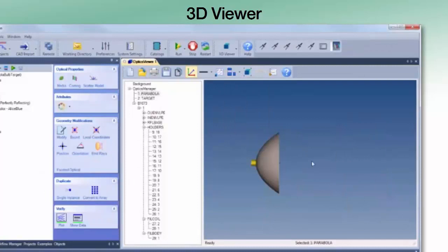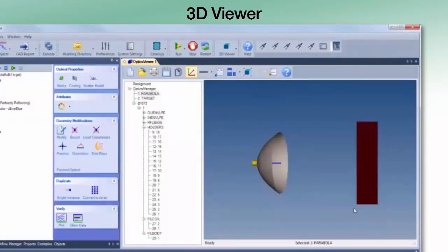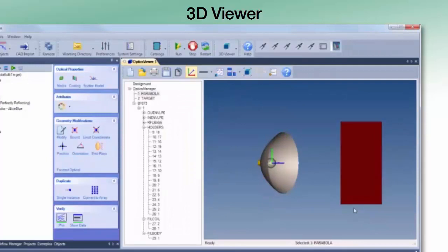So if you happen to be on a system that doesn't have a center mouse button, if I use the actual arrow keys on the keyboard, the left arrow key will rotate by 15 degrees about the vertical axis. So that's a 15-degree rotation. Let me rotate 3 increments, and so I have now rotated 45 degrees about the vertical.